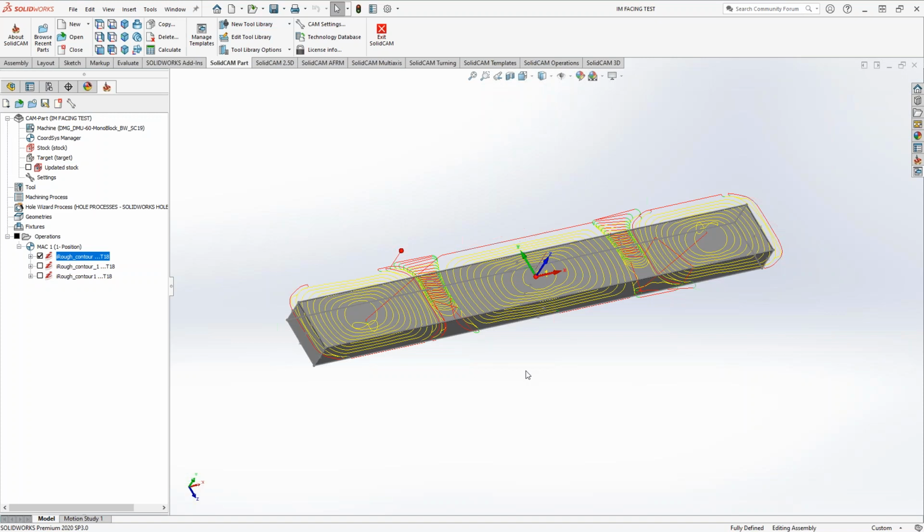Whereas here, we've given it all kinds of freedom. It can go outside the chain, and we've given it the ability to do island moding. So, like Kevin said, this might actually give you a better cycle time, better material engagement, better tool life, just because of all that freedom it has. Whereas with the other toolpath, the third one, it's got those 3 walls it has to account for.